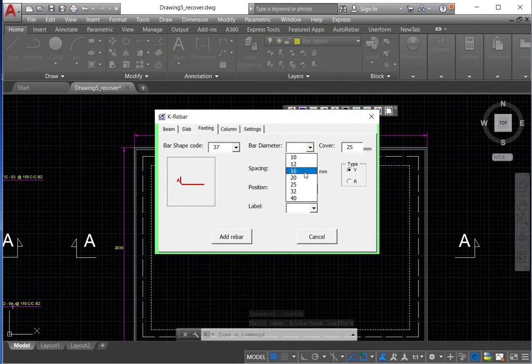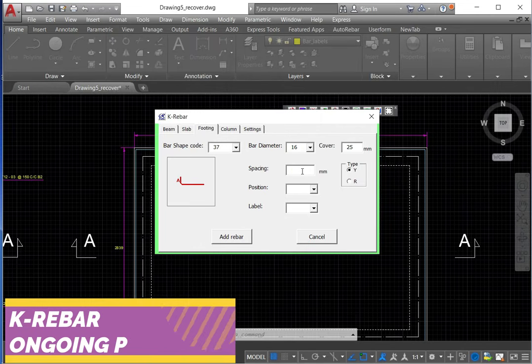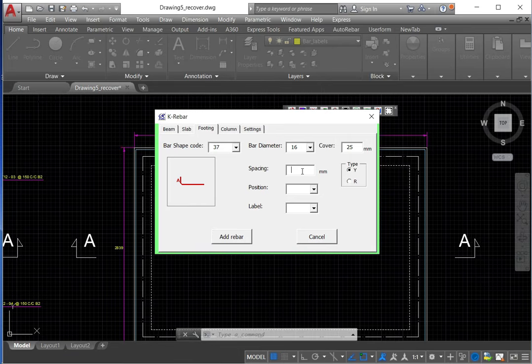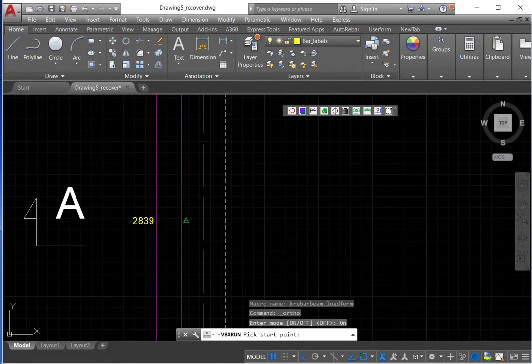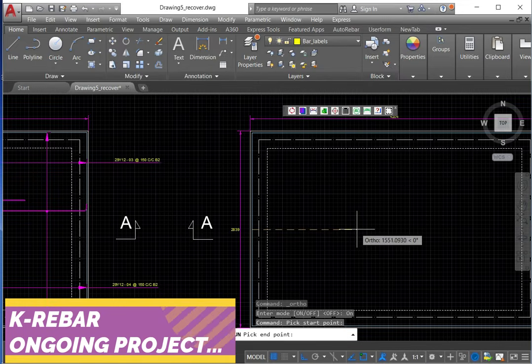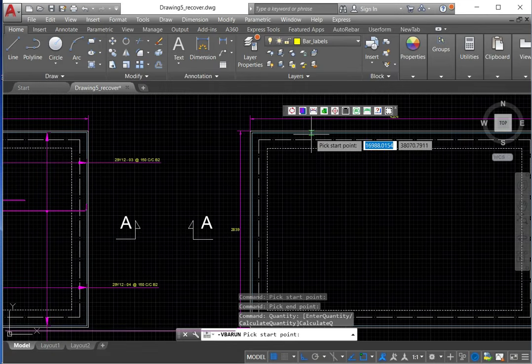As I say, remember this is a fixed end slab. The top reinforcement is more under stress, so there's more. I would take Y16 and spacing 125, and then this will be top one. This will be top one, and take from here to there, to that position.